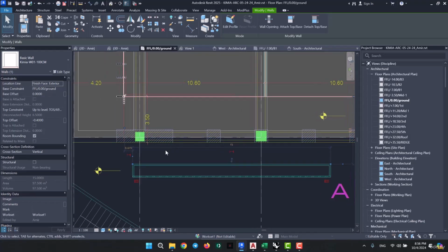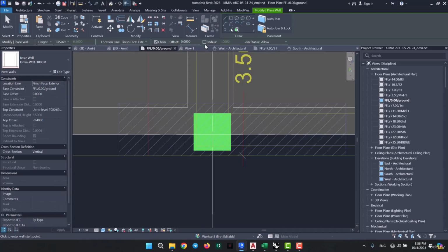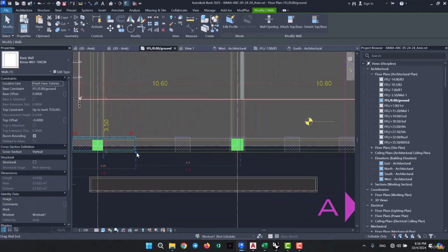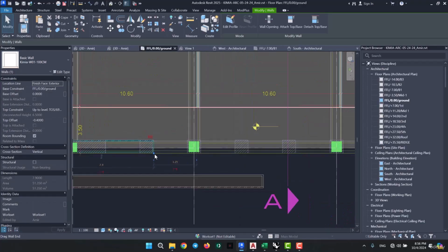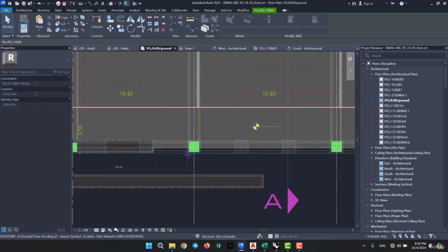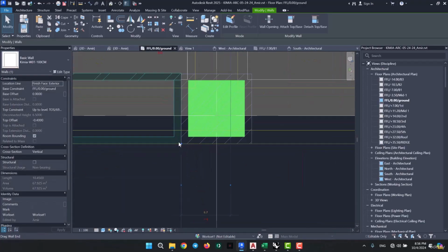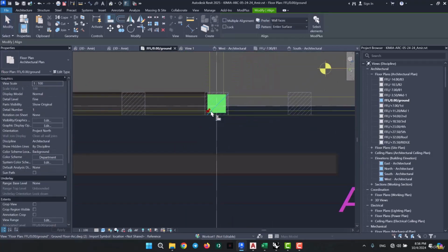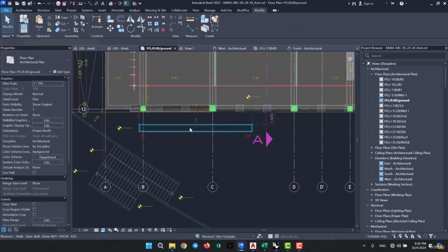So far, I have created this wall type. Now I'm going to go over here and grab pick lines, and then I'm going to click over here to place this wall. Do you see that? There's one that we need on this side. And also sometimes you may have to actually draw your walls piece by piece. For example, for parts like this one, if I stretch this to here and align these two together, actually let's just go ahead and do this whole part together.